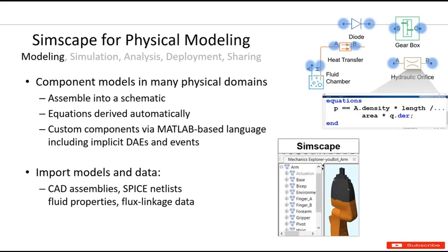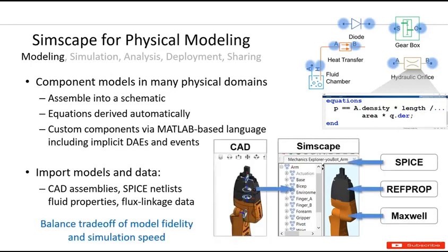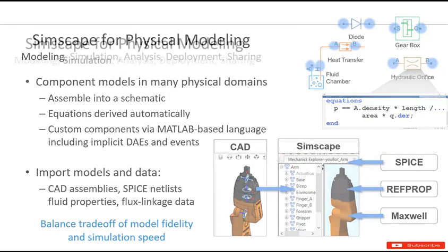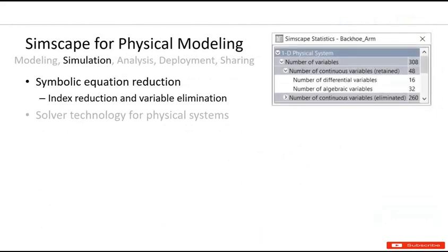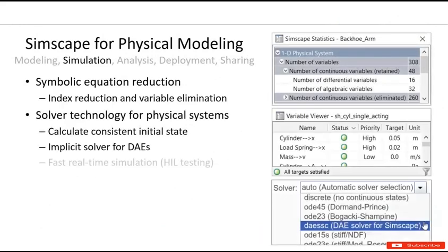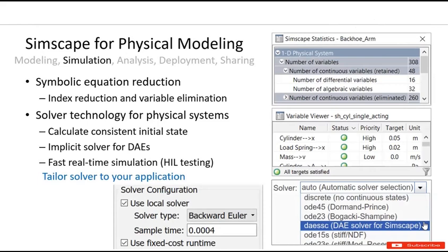So you can bring in those CAD blocks into Simscape and add those additional features around it. Basically the underlying Simscape solver is going to solve all the equations of your model, so you don't have to worry about it. It has the underlying system, the solver technology for solving all these different types of equations.